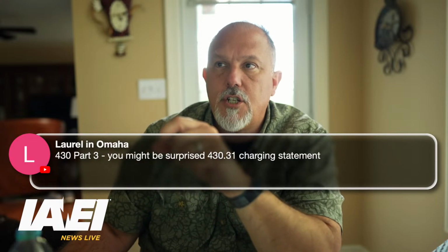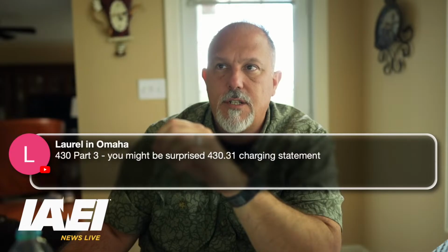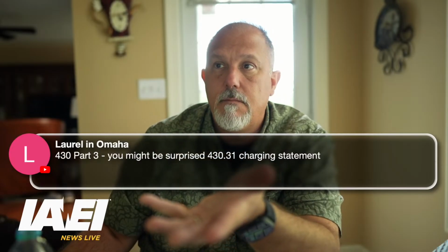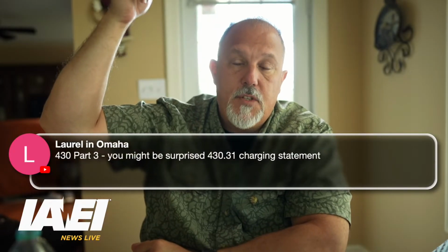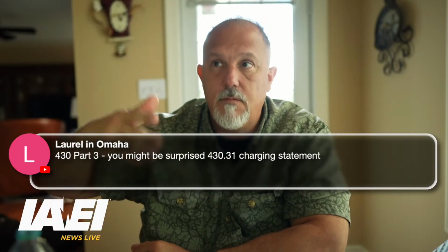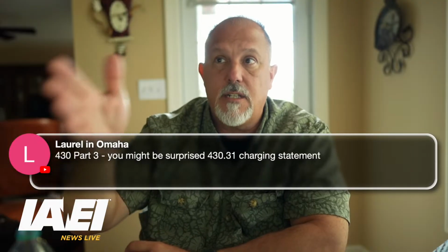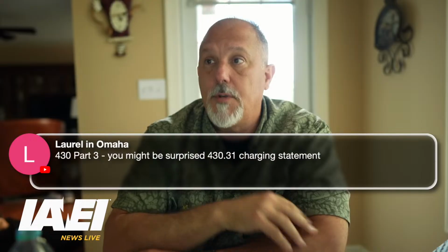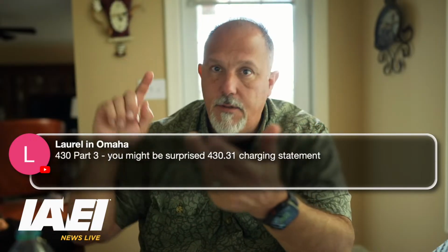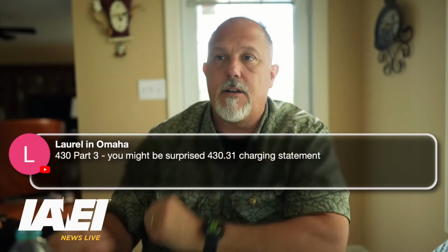Then overload protection, this just says overload protection, so it's very generic. I would say this one would apply to the above statement where it says circuit and everything because it doesn't specifically say the motor. So this is very generic. I would say that's overload protection of the conductor and the motor starting equipment, etc.